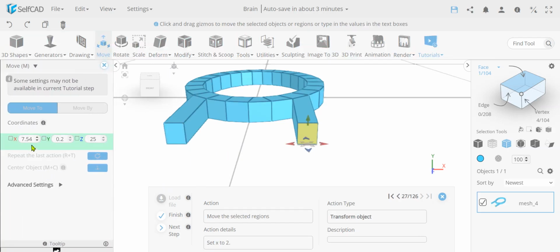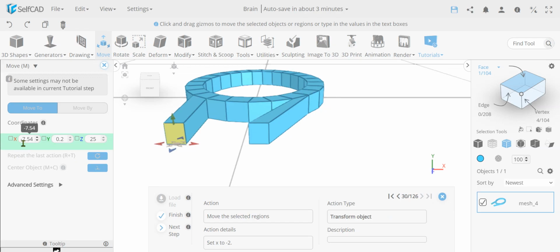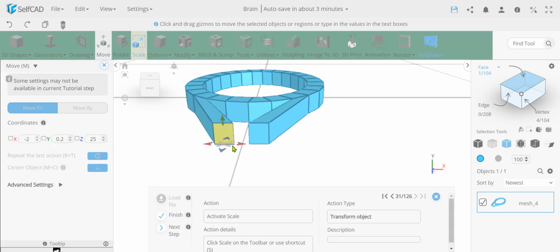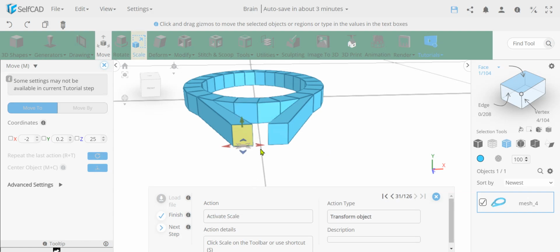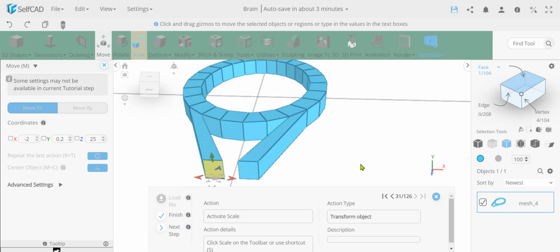And then I'm just going to move the x-axis to 2 and move it like this, and deselect this and select the other one and move it to -2. So they're both symmetrical and 2 from this line. The way you tell positive and negative is you look at this axis over here, and the direction of the line is positive. So you see the direction of the line is positive, so this was moved to positive, but this one was over here, and moving it actually had to be negative. Actually, let's see why. The x is, yes, okay, so it was negative a lot more. Okay, I got confused, negative. So actually it was negative, what, 7 something, so I moved it just -2. So that basically makes sense.